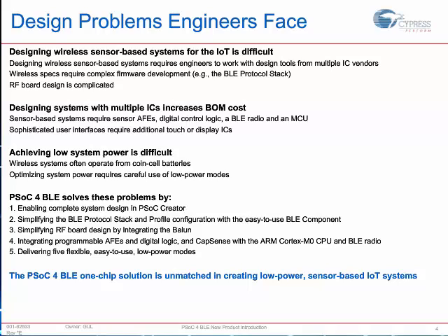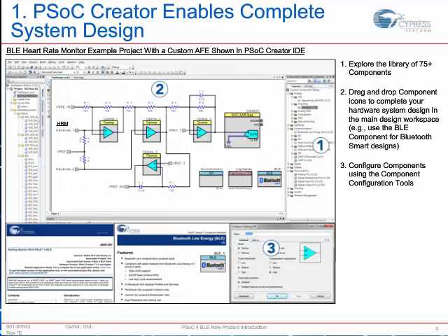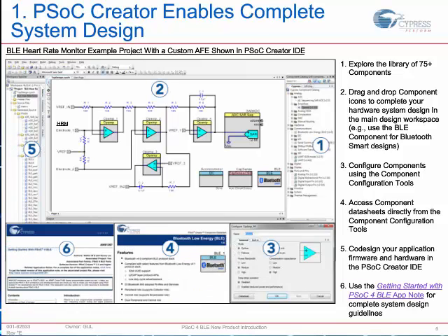PSoC 4 BLE is a one-chip solution, and the solution has a software front end called PSoC Creator. PSoC Creator is a free development IDE from Cypress that is used to create any sort of PSoC systems. And PSoC Creator works in a very graphical or schematic capture-based paradigm, similar to an FPGA for those digital engineers who are familiar with that paradigm.